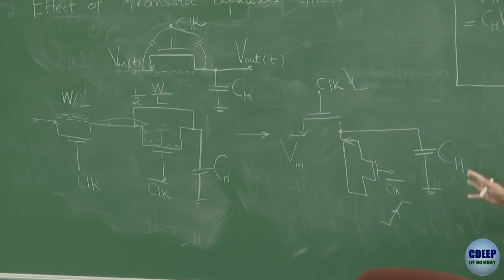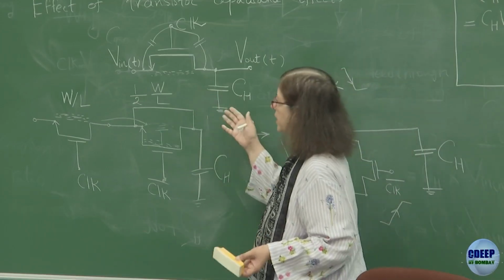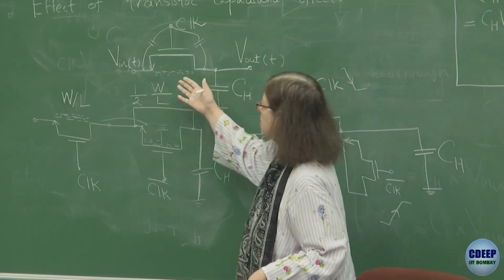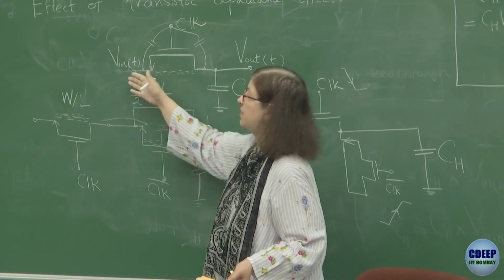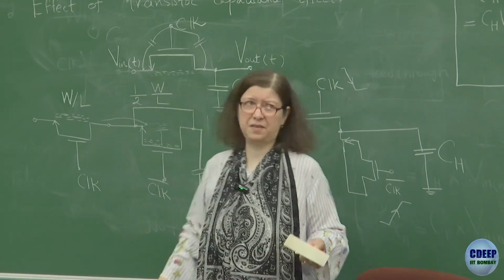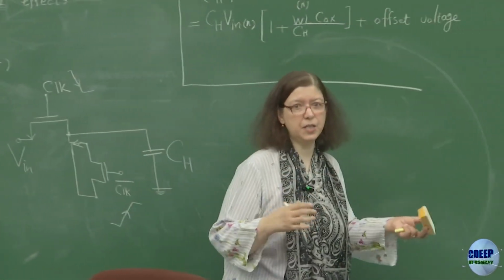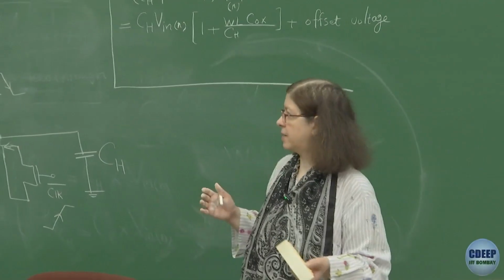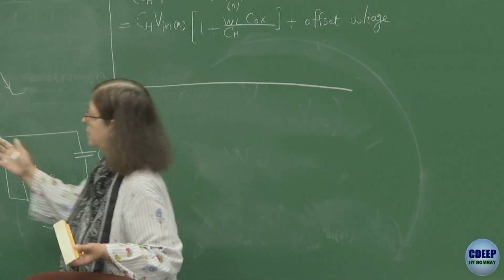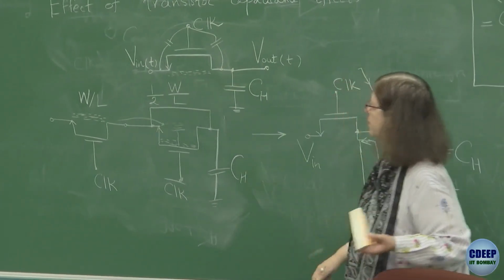So this is helpful because we have to avoid this V-independent charge injection, because as I said, that worst case I consider is only one case which may happen, may not happen, because always some charge also goes into V-in. In fact, what fraction comes also depends how fast clock changes. So there are so many factors affecting the percentage of charge exchange between the two sides. So some charge goes from V-in, some goes to V-in, some goes to CH.